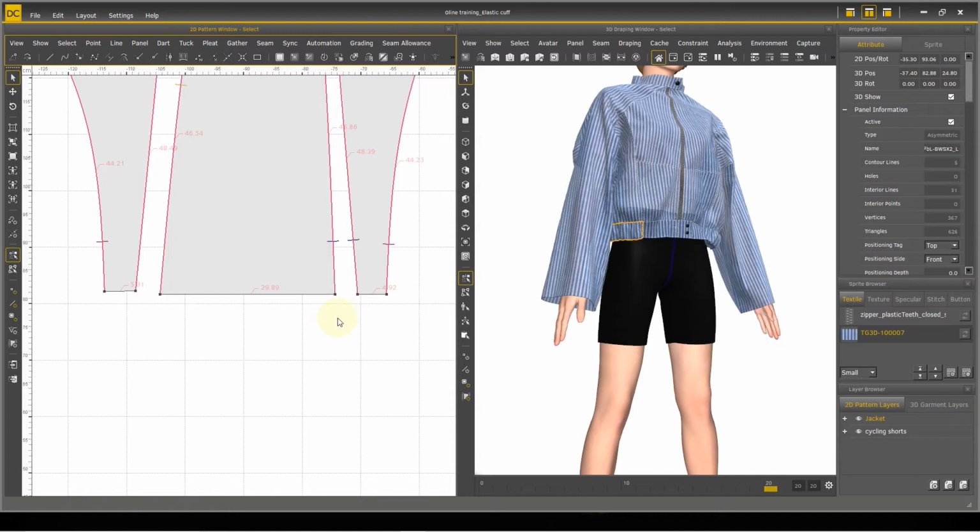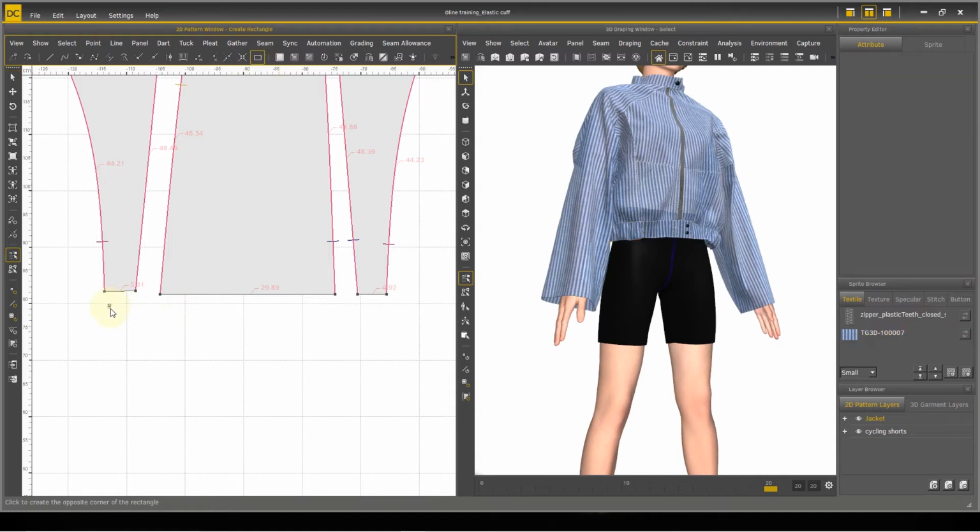So, I need to create a panel of equal length with a width of 3.5 centimeters. Click the icon to create a panel, enter 40 in DX, and enter 3.5 in DY. Here, positive and negative values represent the directions, and then knock them into a panel.